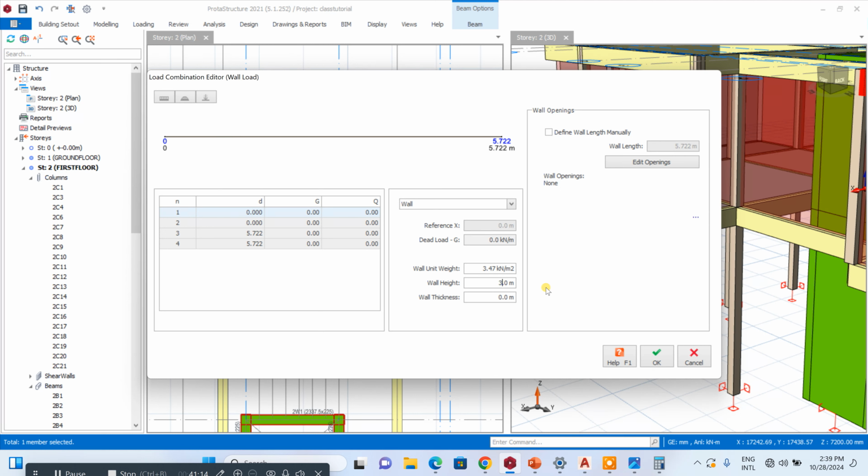Now go to our slab. So we can actually use a slab depth of 120 for our roof. We enter our value as our flat roof is general.